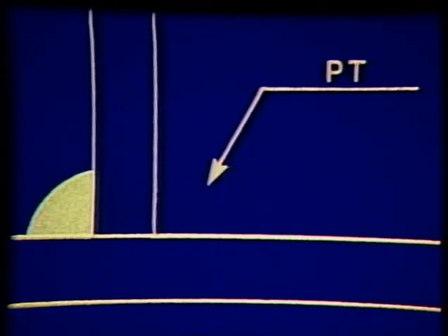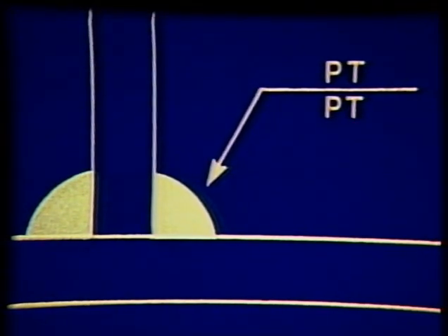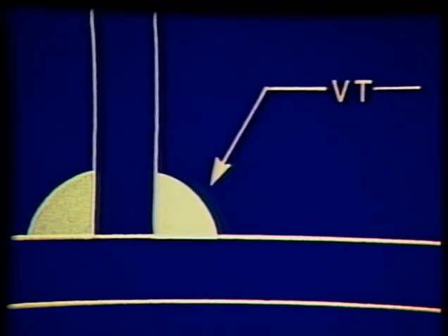If required, the test symbol can be placed on both sides of the line, indicating that both sides of the joint are to be included in the inspection. If it doesn't matter which side is inspected, the symbol is centered within a break in the reference line. In all cases, the inspection is for 100% of the weld, unless noted otherwise.